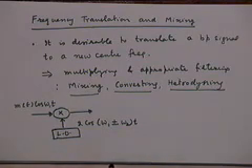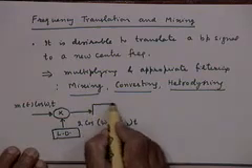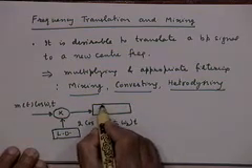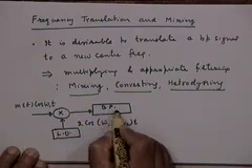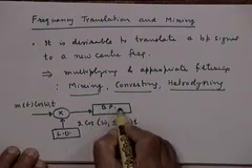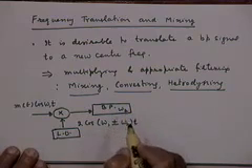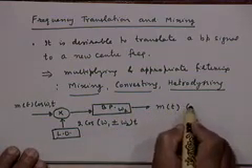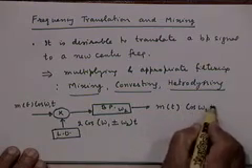But the component that we want is centered around ω2. So what kind of filter do we need here? Not a low pass filter, a bandpass filter with center frequency of ω2, right? And that will lead to your m(t) cos(ω2t).